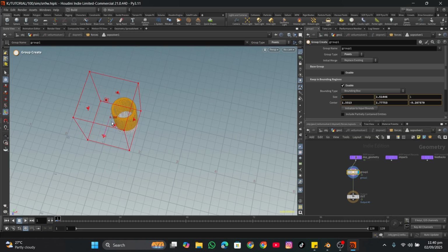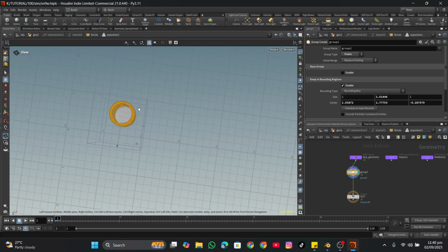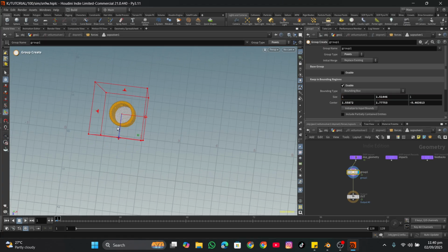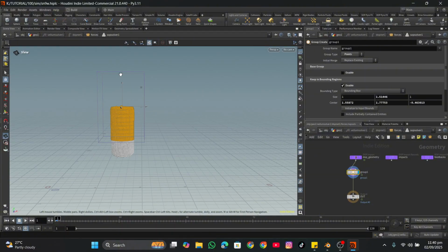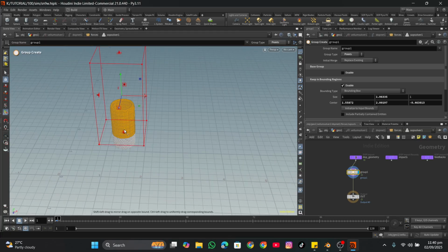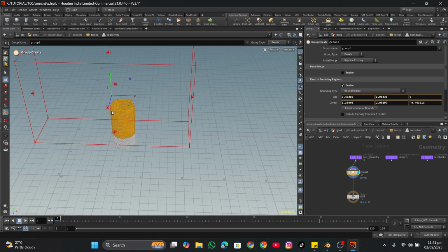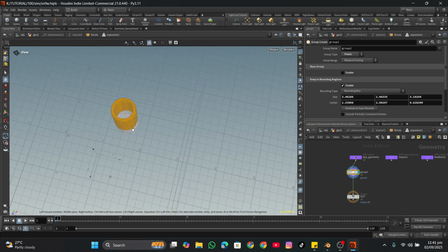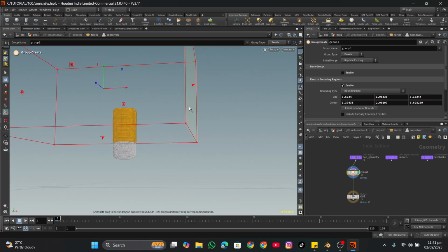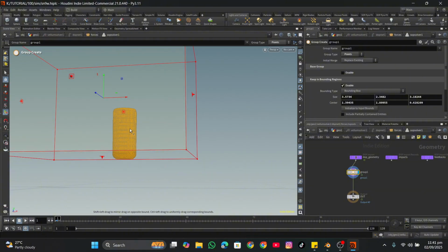So it's not a very professional way of doing it. Some really professional Houdini artists do it with VEX or maybe VOP, but I'm doing it the Blender way, forcing everything to work in the easiest way possible. That's my job. That's what I do, right? So I'm going to scale this cube up, like so. I'm only going to scale it on that axis. I'm also going to scale it on this. So anything that is inside this will be simulated. Anything that is outside this will not be simulated.